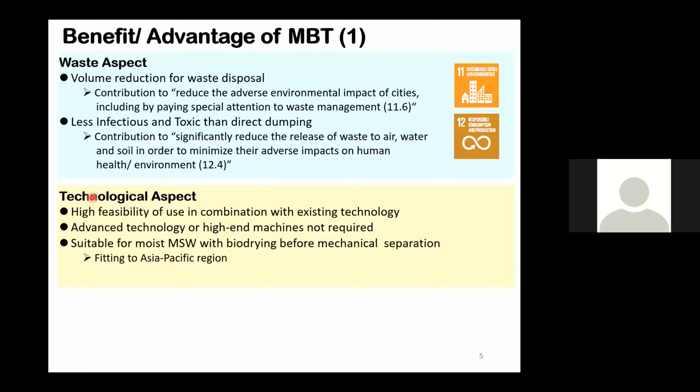I'd like to explain more detail about the benefits and advantages of MBT. In terms of the waste aspect, I repeatedly said that it can reduce the volume and amount of the waste to be disposed of. And since it can improve the quality of the debris, we can also reduce the risk of infection or toxic hazards compared to direct dumping or direct landfilling.